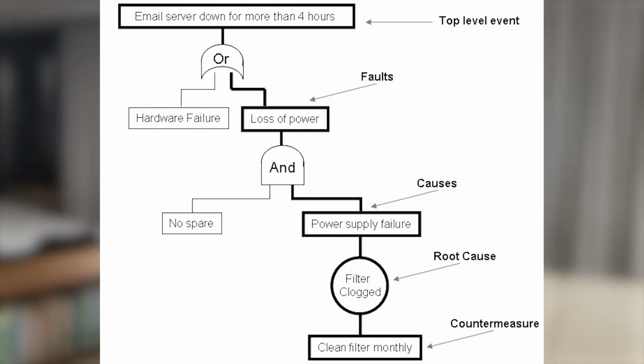To solve the fault tree, we examine all the events and conditions and find dependencies among them. At the end, we use statistical data to evaluate, predict, and improve the future performance of the system. On the other hand, the FMEA is a reliability evaluation design technique. It examines potential failure modes within a system and its equipment to determine the effect on equipment and system performance. Each failure mode is classified according to its impact on mission success and personnel or equipment safety.